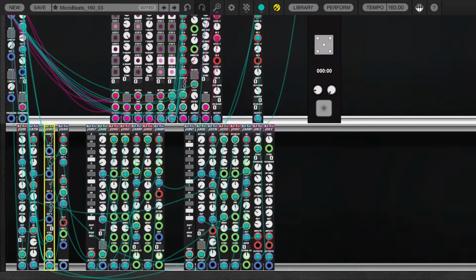So the trigger input pulses are counted, and for every 3 counts a trigger is output here, for every 5 counts here, and accordingly. Again, at the bottom we have a combined output that combines all of these counters into one trigger stream, and by doing it like this we get a pretty complex pattern out of these 4 counters. It's basically modular sequencing.